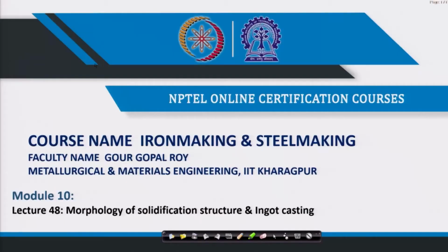In the last two lectures, we have discussed the two fundamental aspects of casting, like heat transfer and segregation. In this lecture I will cover the morphology of solidification structure, and along with it I will also briefly discuss ingot casting, because ingot casting nowadays is not used too much, and only for some forging purposes some ingots are cast. Usually for flat products ingots are not cast today. Flat products are made mostly by continuous casting.